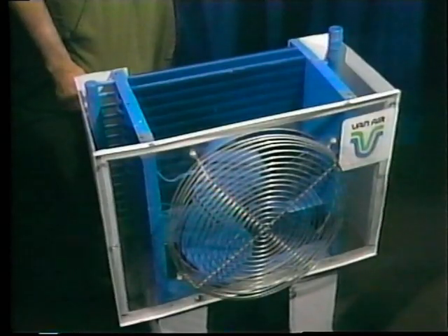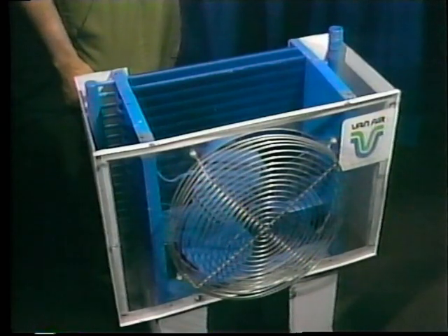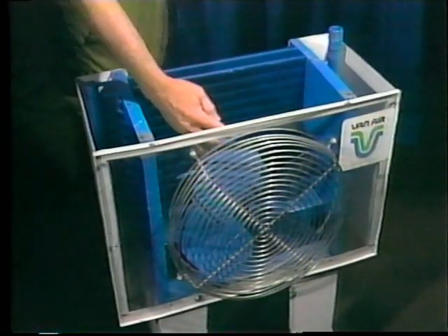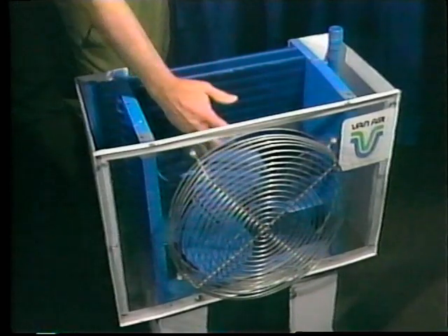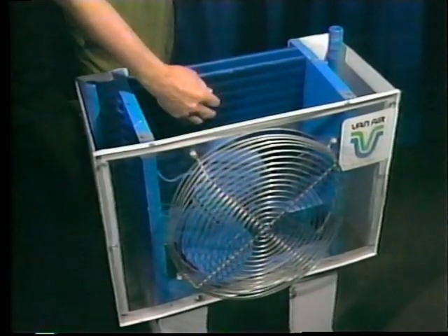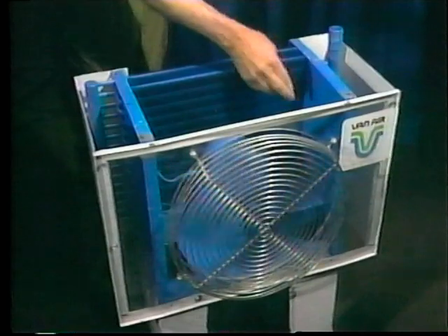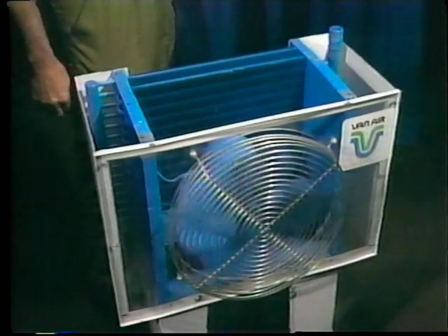There are also air-cooled aftercoolers, which function in basically the same way as the water-cooled. In this case, air is used for the cooling medium instead of water. The cooling air is forced across the coil by a fan. A good water-cooled aftercooler will cool the air flowing through it to within 15 degrees of the cooling water temperature and may condense up to 90% of the water vapor originally contained in the air.